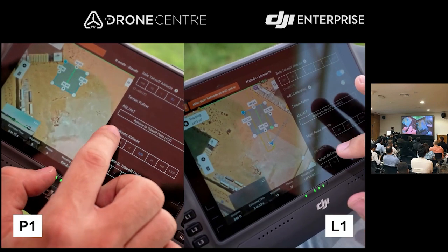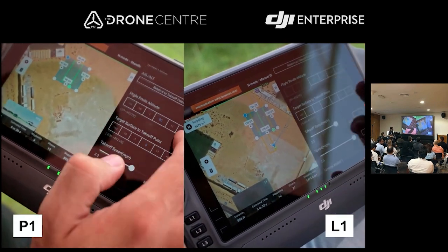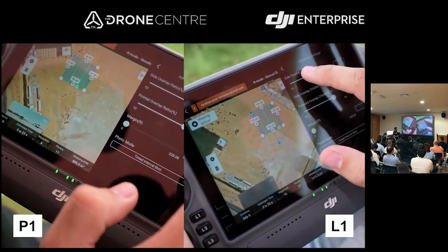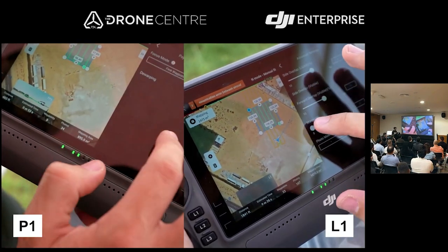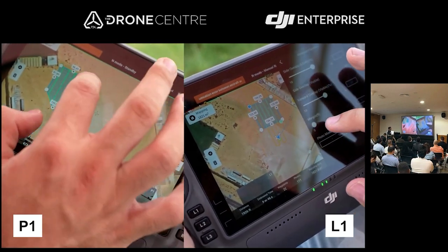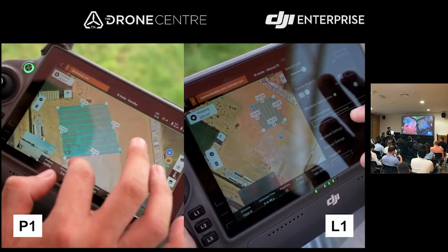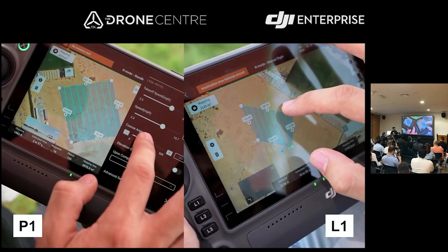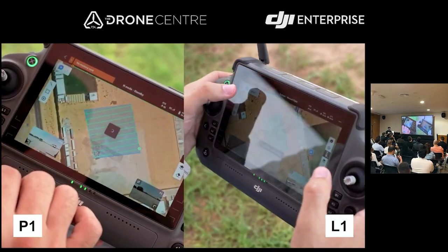all the parameters of your planned mission. So maybe you can plan about 100 meters, 80 meters. In this case, we have used 80 meters, and the planning at the normal 15 meters per second. So both the cameras are planned according to your area of interest. So once you have all the parameters set, again, mapping a mission is what the next step would be.